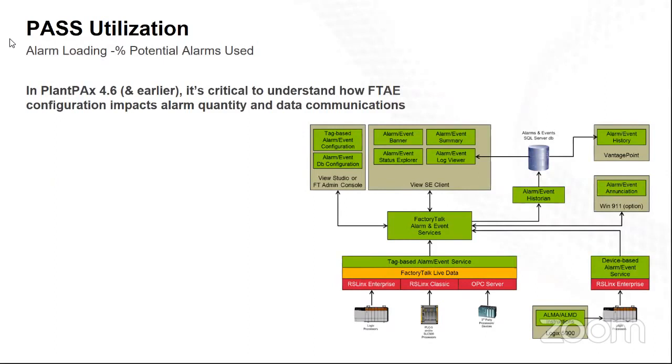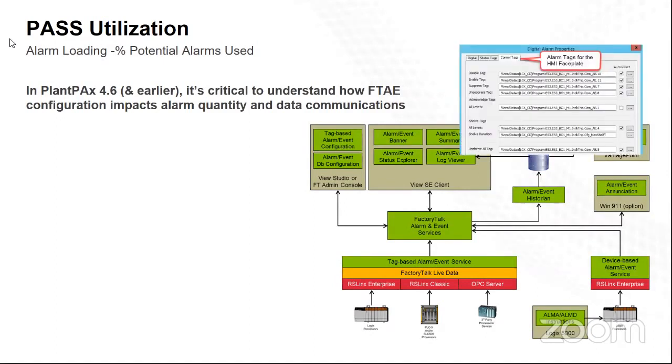Okay. You want to address this one? Yeah, so this is just showing you, again, all the things that you're being asked of if we're looking at the alarming. In this case, if we're using our process library objects, an analog input has a potential of 5 alarms. Each one of those alarms, because of the ISA 18.2 alarming standard, also has shelving, disable, and everything else. And it's a tie-in to the controller. The controller becomes the master. So you're now adding about 15 data points that have to be recorded inside of that controller that are on scan as a potential alarm.